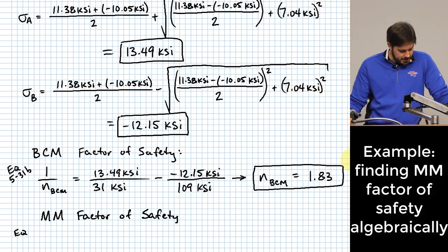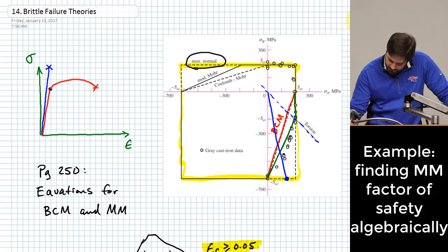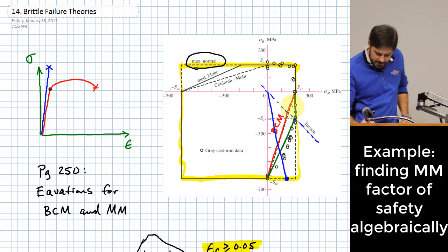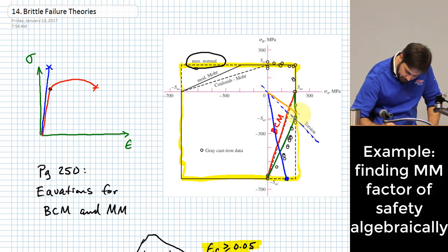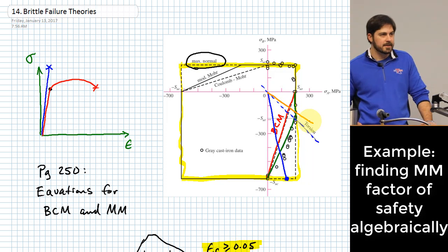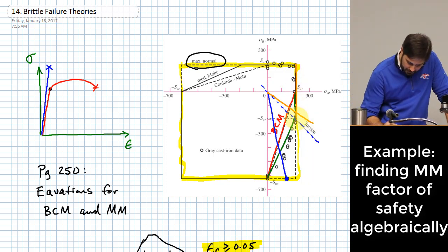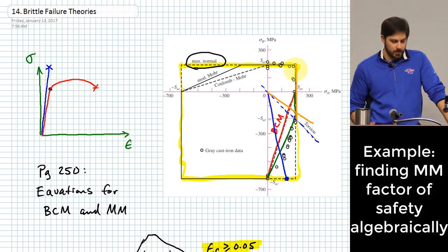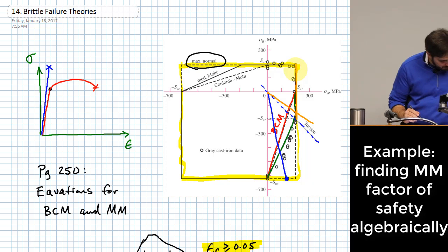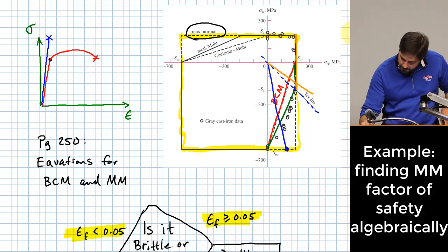Since I have a ratio less than 1, where that puts me on the failure locus that I had way up here at the beginning, it means that my load line is going to lie somewhere up here above that break, which means I'm still on this vertical line. And because of that, we would be using equation 5-32a.